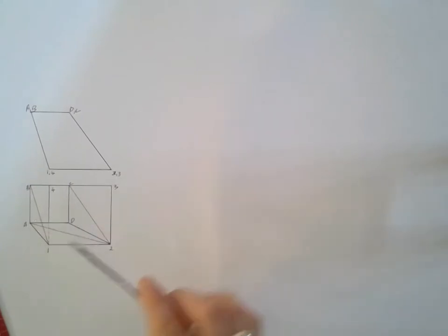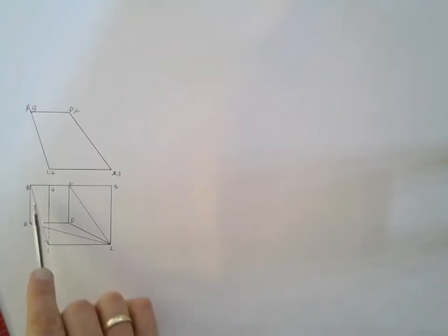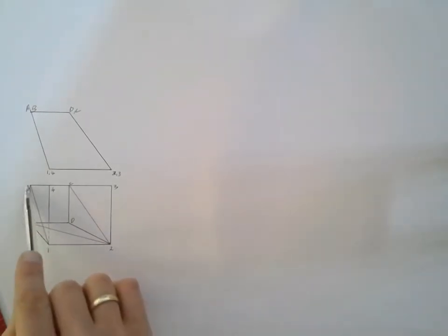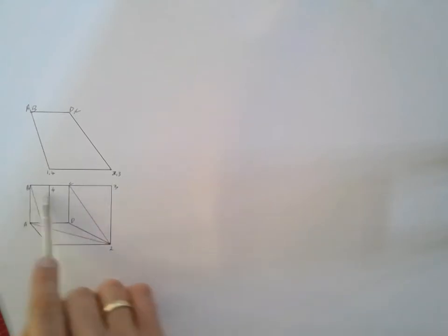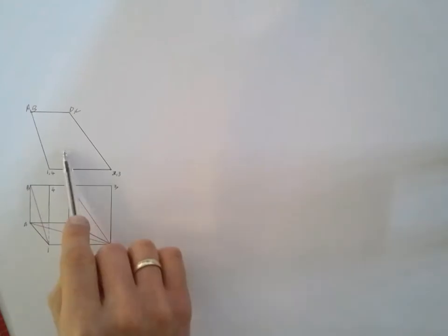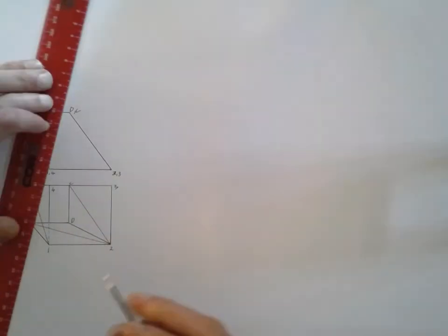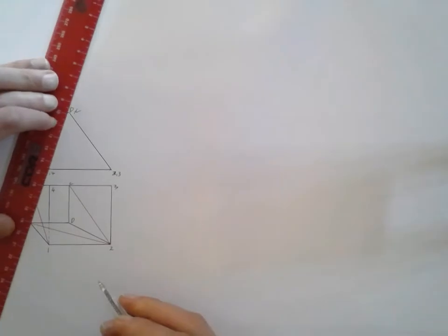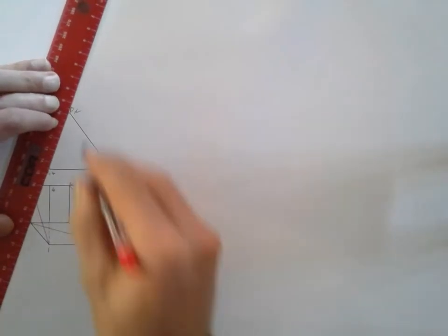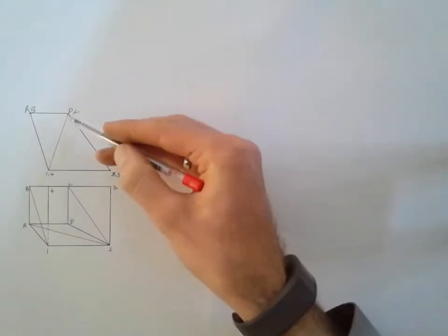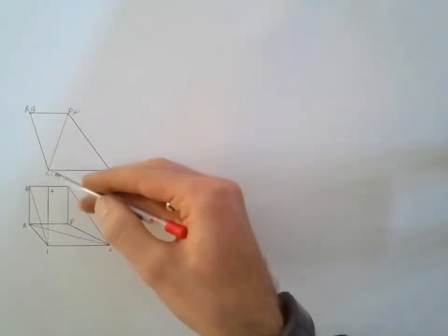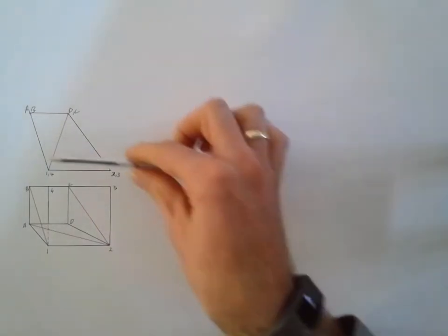The other side, which you can't see at the moment because it's standing straight up, it's vertical, is the side over here, which is the side BC34. But that side's true shape is shown in your front view, so you're going to go and triangulate your front view so that you have 2 triangles to use there for your construction. And that line that I've now drawn down from the top corner to the base, that's already a true length because we have a vertical face shown in our front view.